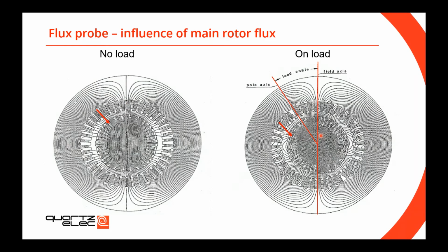So what we do, we move the angle of that rotor. Then have a look at this picture now. You see that the longest coil on both poles has no influence from that main flux. So you can see the clear spot here. When you take the reading with your flux probe, you can say that the biggest sensitivity of that reading is around coils 6 and 5.